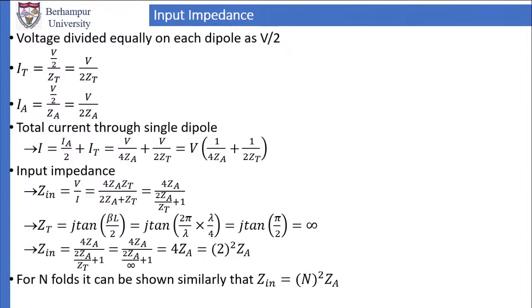All power will not be radiated. Some of the power will be radiated, some will not be radiated. The portion that is not radiated is because of transmission line. We have discussed transmission line and we have seen that transmission line does not radiate. Two-wire parallel transmission line will not radiate because currents are in opposite direction in the transmission line. So transmission line will not radiate. Contribution due to each line will cancel out. So that mode and the radiation mode, both will be considered here.